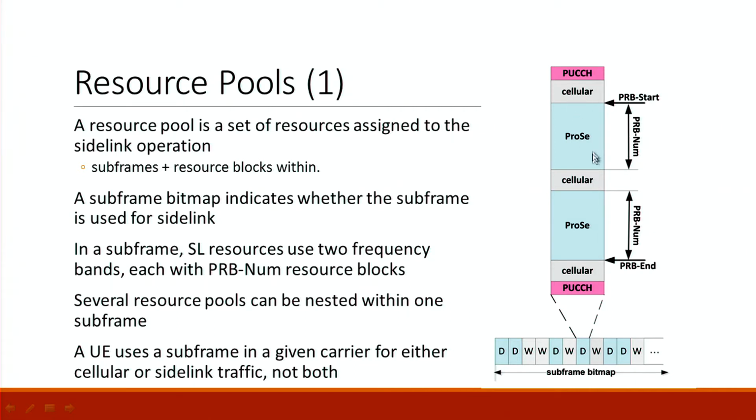So these two sections are of the same size. It will tell you how many subcarriers you can use, starting from which subcarrier and ending at which subcarrier. As you see, it's very easy to control exactly how many resources you are setting aside for D2D communication and how many you are still using for uplink communication. The eNode B in this way has very tight control of how resources can be used at any time, both for cellular communication and for D2D.